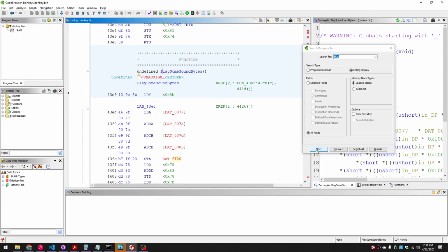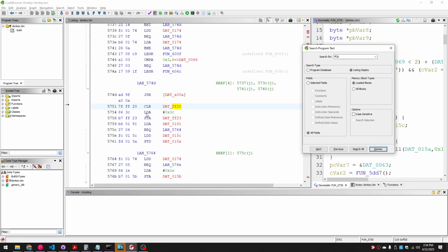Who else writes to FF20? In this block of code, we just seem to be clearing FF20, and it's right after we're making a call to the joy-in, the joystick routine. And also right here, we seem to be writing to this hardware register, which controls the master select switch for the audio. And I believe by setting it to this, we are setting the bit to turn on sound. So it's possible this is about restoring the use of the DAC for the sound after querying the joystick.